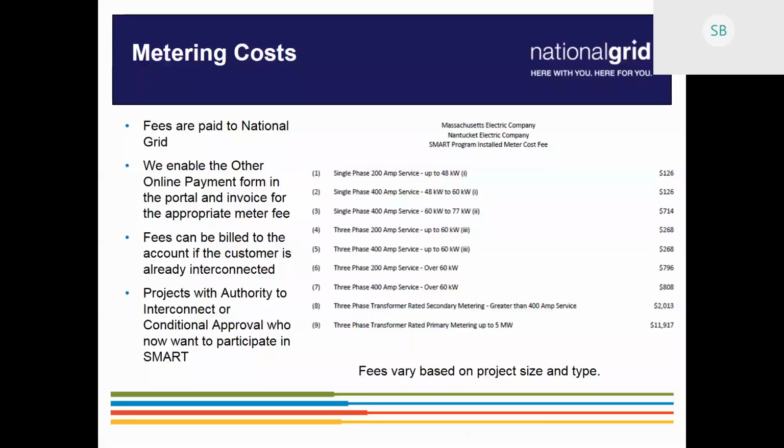We would need the impedance information and the generator step-up transformer information. We need the impedance information between the substation that connects to the transmission system and the point of interconnection of the project, and the GSUs and the generator unit megawatt capability.